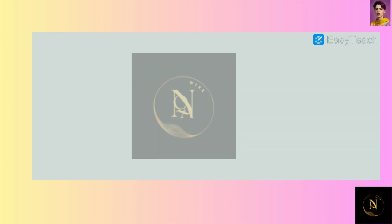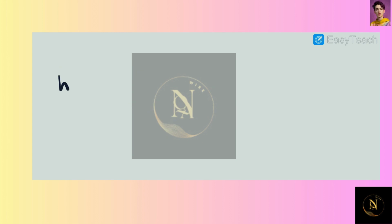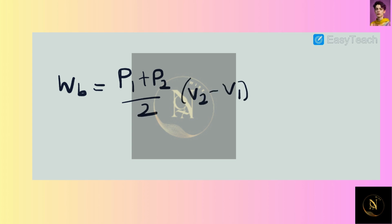So from the mass balance, what this allows us to do is we say that Mi is equal to M2 minus M1, which is going to be equal to 459.9 all over T2 minus 0.1949. Now, since the spring is a linear spring, we can also calculate the boundary work by saying that the boundary work is equal to P1 plus P2 all over 2 times V2 minus V1. And by plugging in these quantities, we see that the boundary work is equal to 41.25 kilojoules.